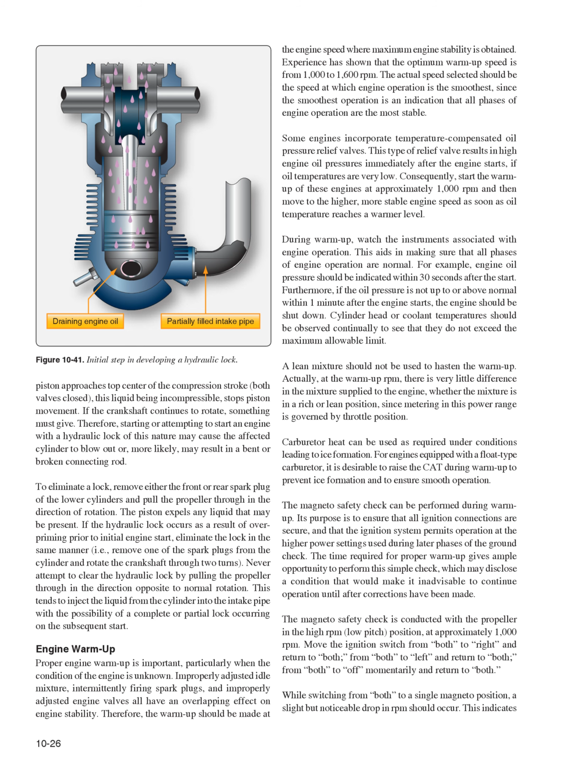Carburetor heat can be used as required under conditions leading to ice formation. For engines equipped with a float-type carburetor, it is desirable to raise the carburetor heat during warm-up to prevent ice formation and to ensure smooth operation. The magneto safety check can be performed during warm-up. Its purpose is to ensure that all ignition connections are secure, and that the ignition system permits operation at the higher power settings used during later phases of the ground check. The time required for proper warm-up gives ample opportunity to perform this simple check, which may disclose a condition that would make it inadvisable to continue operation until after corrections have been made.